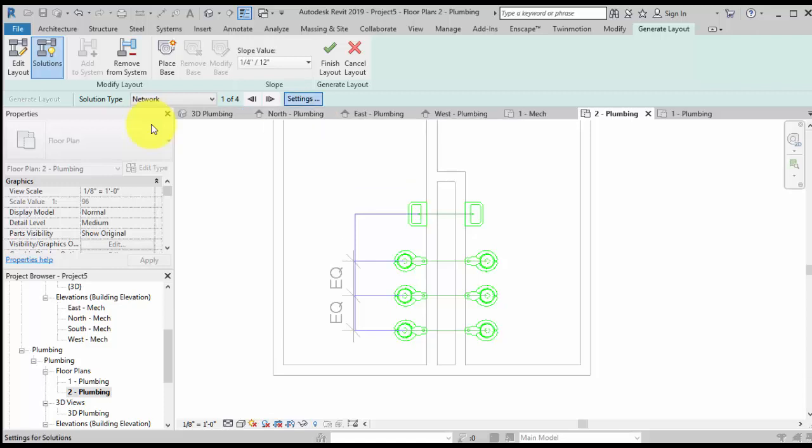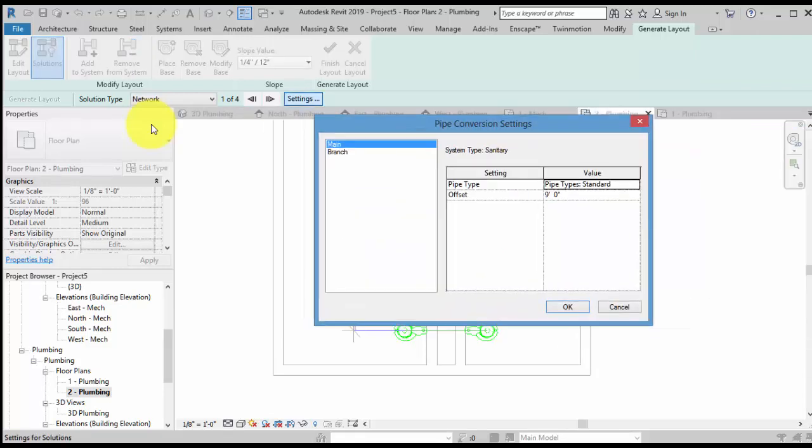Now the next very important thing that we have to change is in the settings. We have this main and branch, and whether the main is lower than the branch. What we're probably going to do is make the main plumbing and the branches identical height, so we reduce redundancy. In a more complex system, you might want to make the branches a little higher, and the main a little lower, to create more pressure. So this is the design of it. We're going to make everything roughly a foot, so they are identical, a foot each.